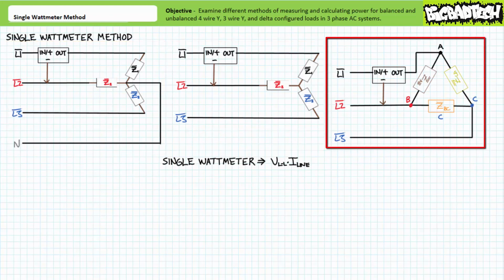Essentially, the opposite problems hold true in the case of balanced delta configurations. In this application, the voltmeter portion of the wattmeter appears to be reading voltage correctly, as loads in delta configurations directly experience the line-to-line voltage. However, loads in balanced delta configurations don't directly experience the line current, but rather a smaller portion of line current. Taken in isolation, this wattmeter's reading is again extremely suspect since it's artificially inflating current.